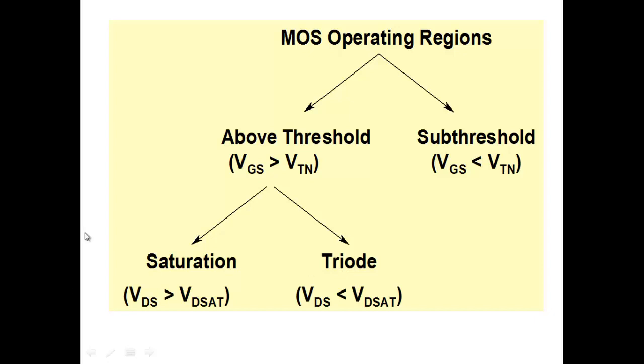And so these are the places when you look at above threshold, when I use my MOSFET. As I said, above threshold means I have significant current flowing in my device. So when I'm talking about the MOSFET as a switch, in digital we mostly look upon the MOSFET as a switch. When a switch is on, I'm thinking of my MOSFET as biased above threshold voltage.